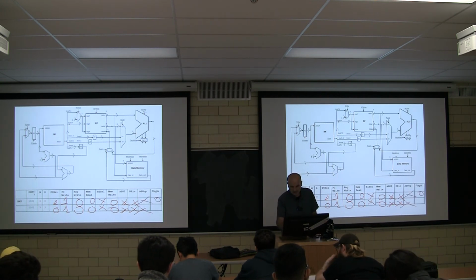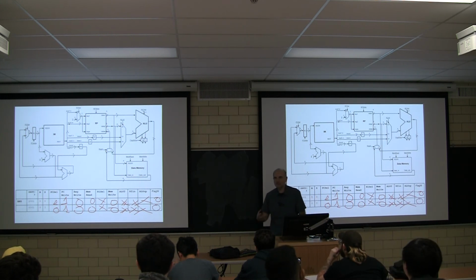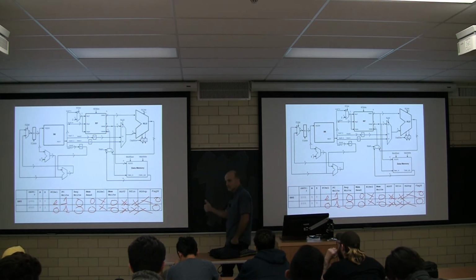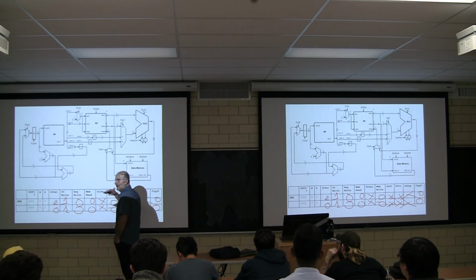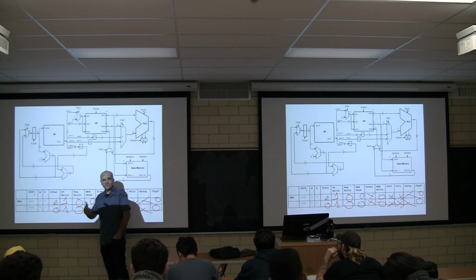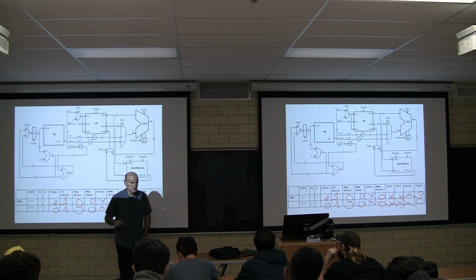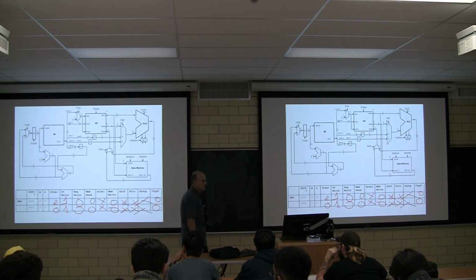Are we going to change the flags? Absolutely not. So notice anytime there is an element that's a storage element visible to the programmer, we have to set values there because it's whether we change them or not. And the only element that's visible to the programmer that changes from a branch is the PC. Everything else should be zeros. Okay. Everybody okay with this? Okay.